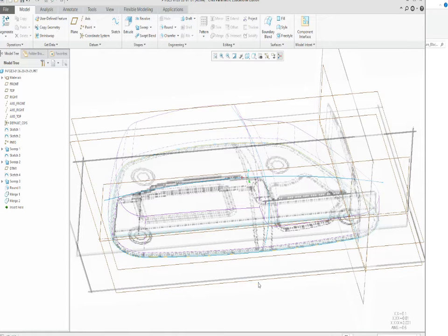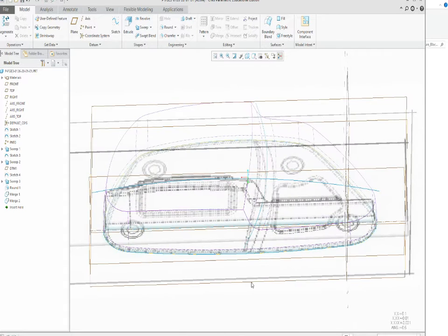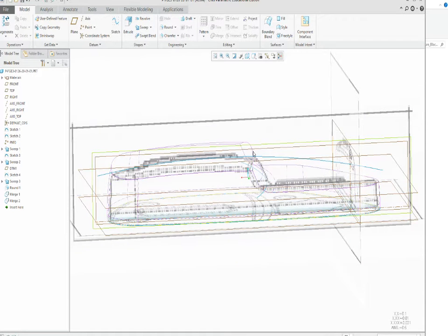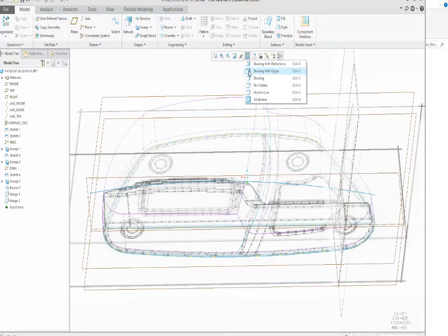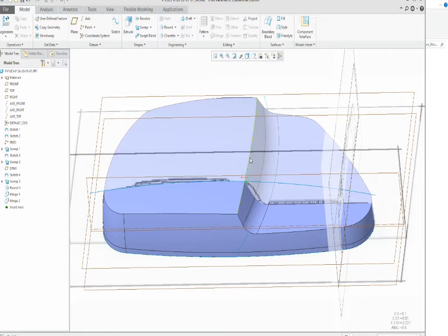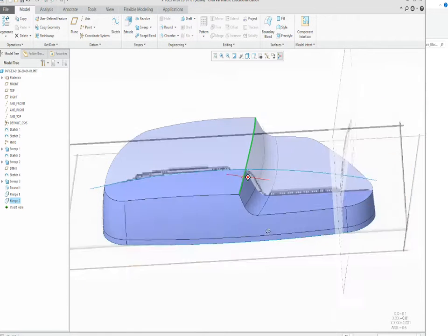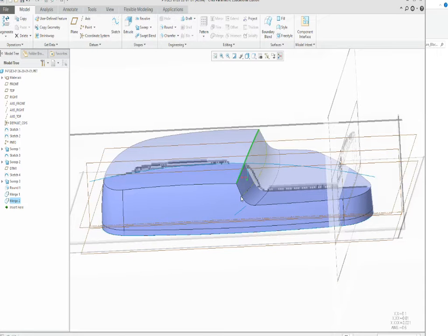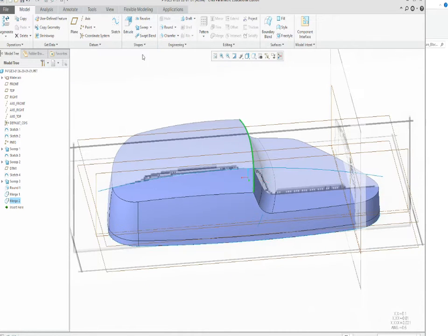So let's look at fillets for the design. I want to put a nice tiny fillet here and still make it machinable on the inside. So if I go with a tiny fillet on this edge, let's go back to shade mode. On that edge right there, if I were to put a large fillet on that, then if it were to go inside on the profile, it would have a tendency to get smaller. So you guys make the guess there.